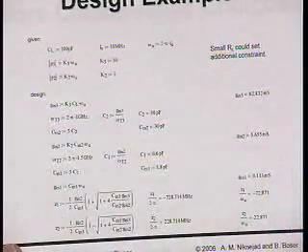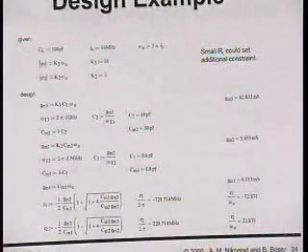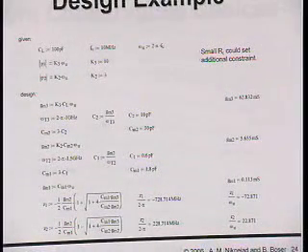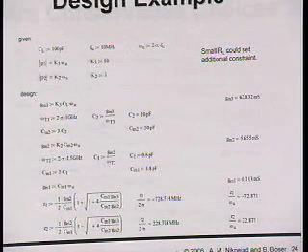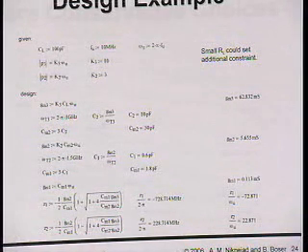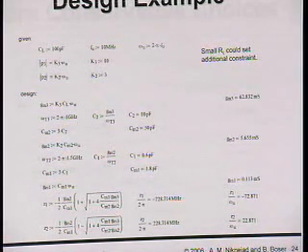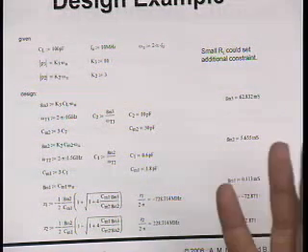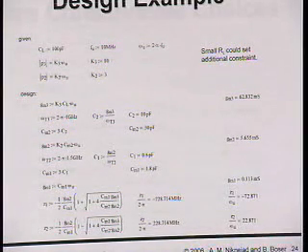So this gives you a design that then you go into with a simulator and you tweak to get it to work right. Because it turns out that the approximations that we made, right, we forced the poles to be on the real axis. If you're aggressive, you can move the poles off the real axis and make this thing even faster. So that's not necessarily the best solution, to put the poles on the negative real axis. You could split the two higher poles and actually get a little bit of peaking but get faster settling time. So you can play games with this and get pretty good performance.